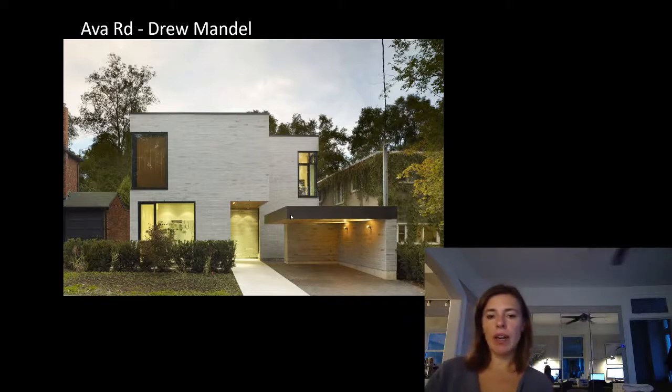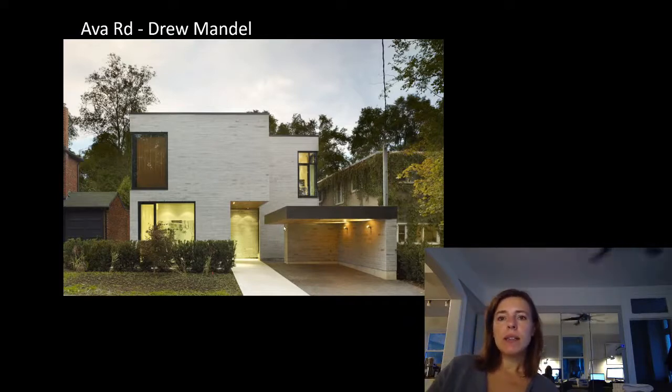We weren't using concrete, so steel. Engineers tend to get into their head this rigorous linear system where they would have put a beam here and a beam here and maybe cantilevered a series of things out here. But what I did was take a member from here to here in a simple span, and then cantilevered out something this way to pick up this corner, and then cantilevered out from this point here as a simple span to my crossing member, and then cantilevered out to this tip right here.